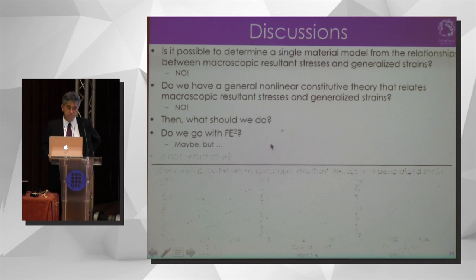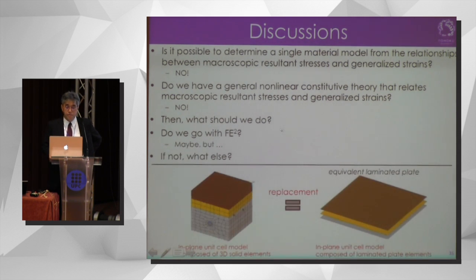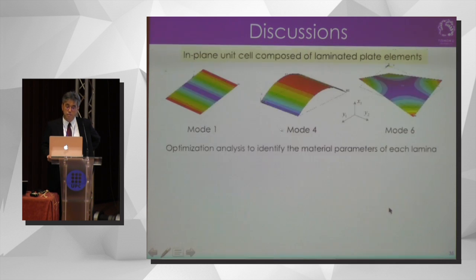Maybe. But if not, what else? One of the solutions would be the replacement of this solid model by an equivalent plate model. That is, we replace this in-plane cell model composed of 3D solid elements by an in-plane cell model composed of laminated plate elements.